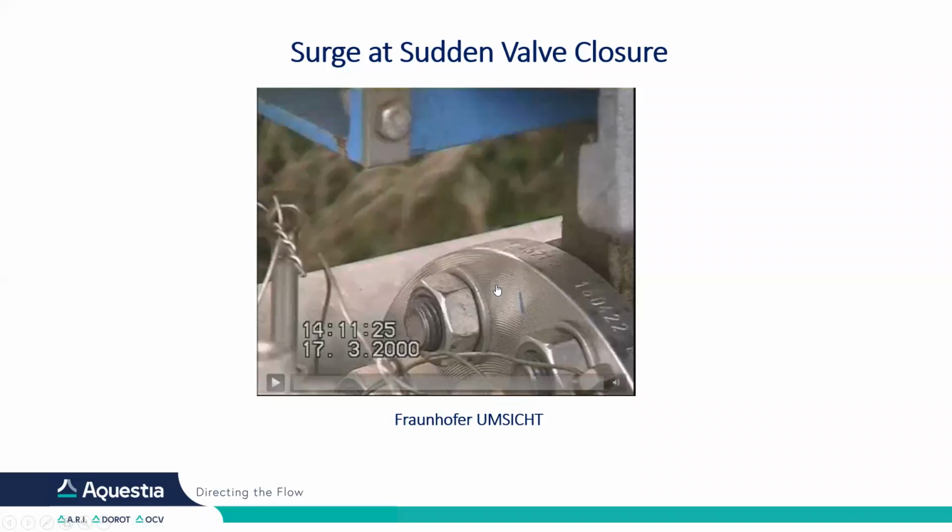This video was taken in this experiment without any protection, okay? Only sudden closure of the isolating valve. What I would like you to see and hear is what happens when they close the valve. You will hear the water column separation. You will hear the water column move forward and return back. The slam, okay? And you will see how the pipeline shakes.